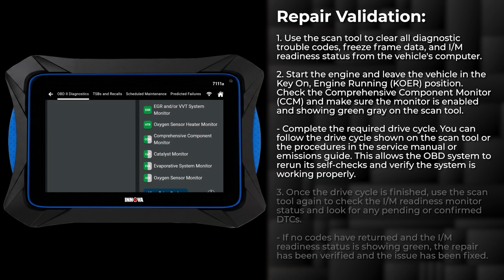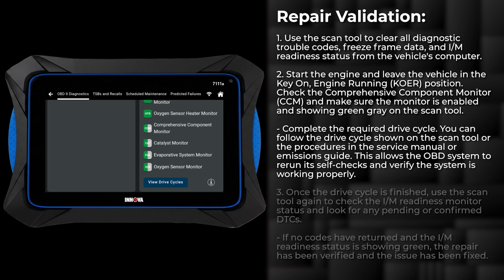After that, complete the required drive cycle. You can follow the drive cycle steps shown on the scan tool or use the procedure listed in the service manual or emissions guide. This allows the OBD system to rerun its self-checks and verify the system is working properly.